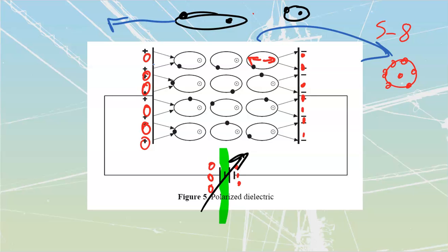Anytime that we take our dielectric and stretch the rubber band so far that it snaps, this electron is free to move. That's when we have exceeded what's referred to as the dielectric strength. We've just turned it into a conductor. It's a conductor made up of what we would call insulating materials, but it is still a conductor.